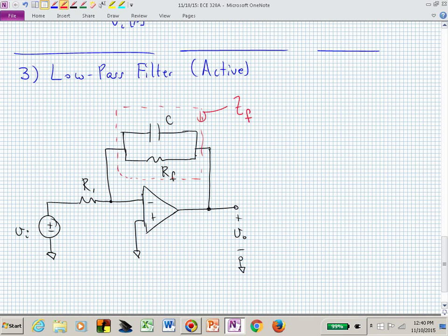One, it's probably much less expensive. It's much less massive in terms of weight if you were worrying about weight issues, and you can accomplish similar features. So that's why you're always seeing these C's and not any L's, but in this class I might throw L's around. In a real world application, you probably don't want to be using L's as liberally as you might want to use C's. Don't really put L's on an integrated circuit.